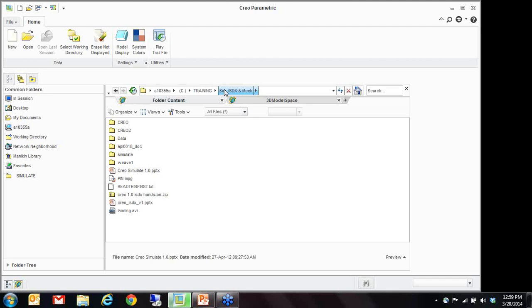And within Simulate, when you do assemblies, you have a lot of model setup options, like say, are two plates, for example, in contact? Are they bonded? That means as if they are fused together. Are they free? That means they can move with respect to each other. So a lot of my customers, at least in the ag industry over here, use Simulate to analyze their huge frames for tractors, or loaders and stuff, if that's the question.